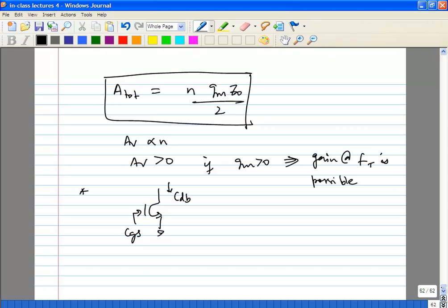So the transistor capacitance is not symmetric between the gate and the drain. And remember that you want equal delays on both the lines, which means you need to be careful. The two transmission lines will never be the same, even though in an ideal case you would want them to be the same. Once you start taking into account transistor parasitics, you will have to adjust. So you can absorb the CGS into the shunt C of the transmission line. You can absorb CDB into the shunt capacitance of the transmission line on the drain side. Except that now those two transmission lines will be slightly different.